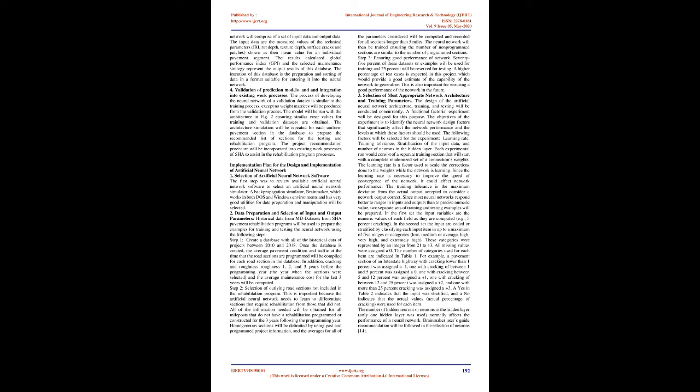Several pre-processing steps will be taken for smoothing, outlier detection, normalization, mean removal, and decorrelation. As the pavement deteriorates, roughness typically increases with time. Data records where the IRI measurement is less than its previous IRI reading, while no testing or rehabilitation treatment had happened, will be considered outliers and will be ignored in the database created. This allows the creation of a network map of pavement areas that need testing and rehabilitation.